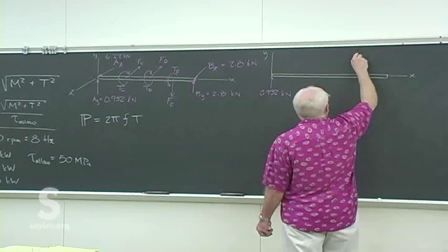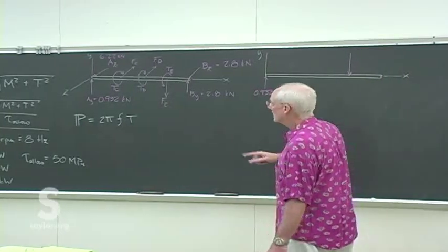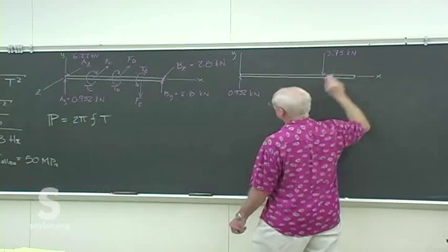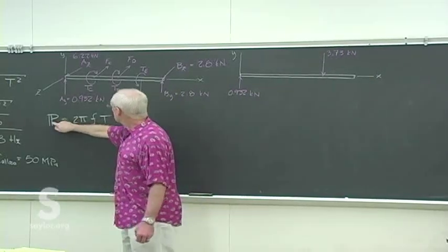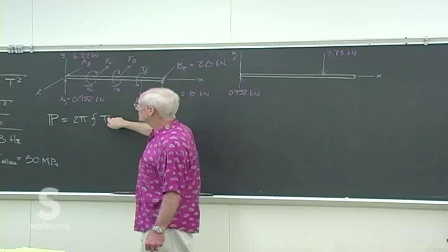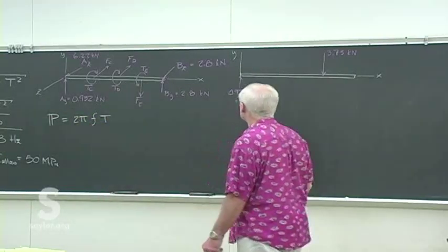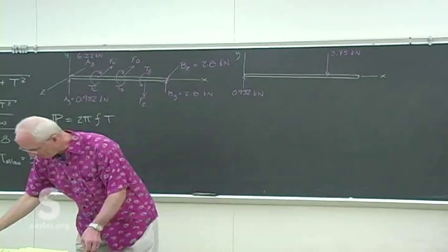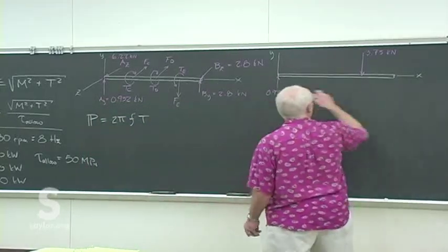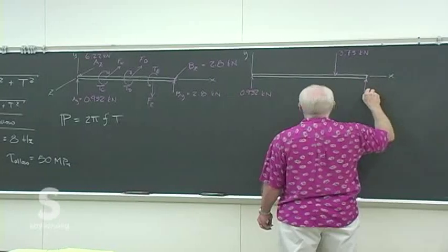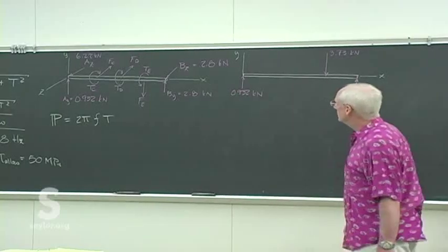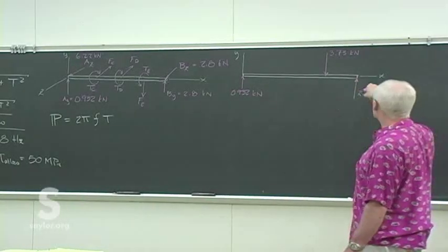which will be something like that, and we know that to be the 3.73 kilonewtons. Remember, that's from finding the power coming in, the known frequency, figure out what the torque is applied at E, then from that torque and the radius of the gear, find out what the force is. And then the 2.8 due to the reaction BY. BZ we don't see in this view.